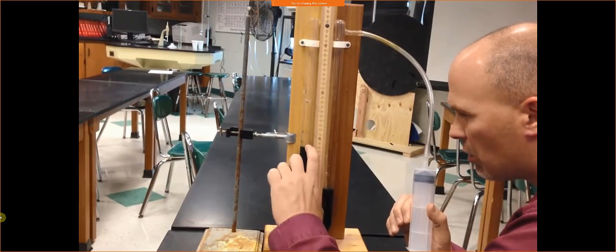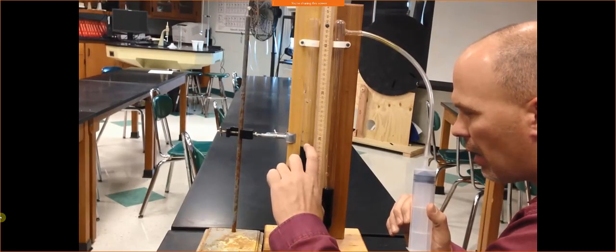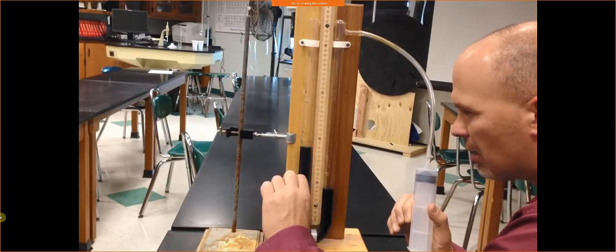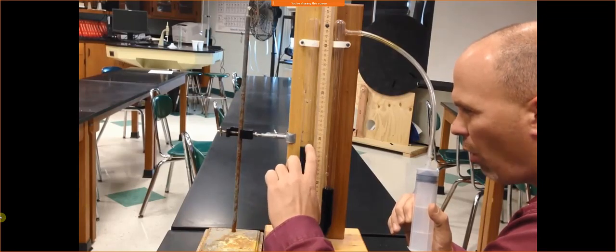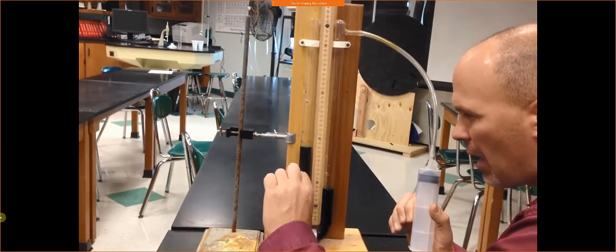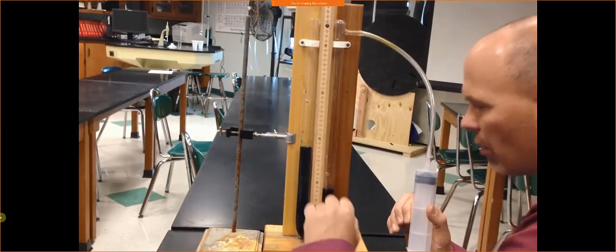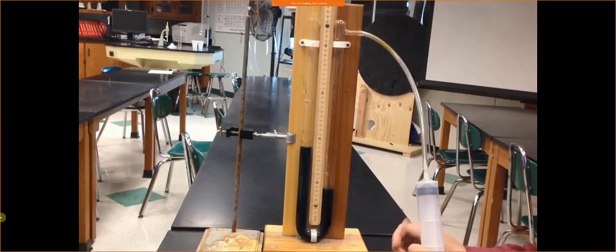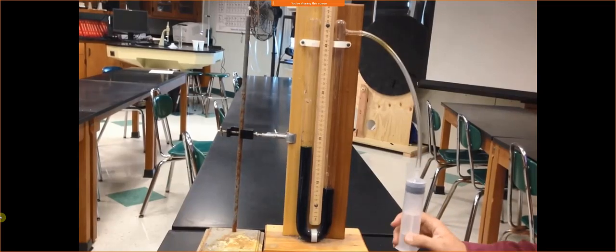Remember, we're supporting a certain weight, and for the same weight, mercury is going to be a lot less volume. So if this was water and I were to convert it to mercury, we're going to use 190 millimeters, divide it by 13.6, and that would be the height in mercury. So we can certainly get there by doing those differences. So that's all the basics of manometers.